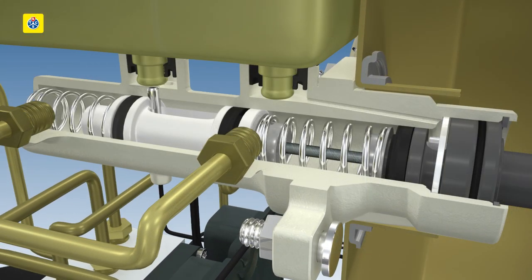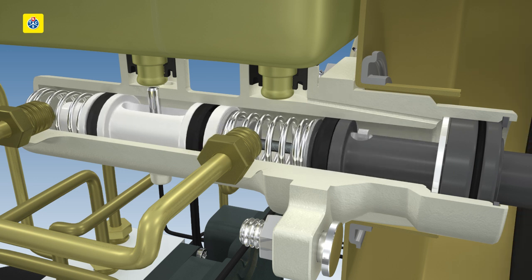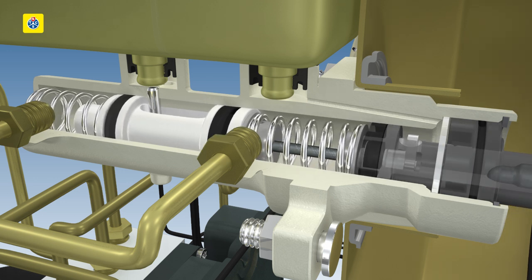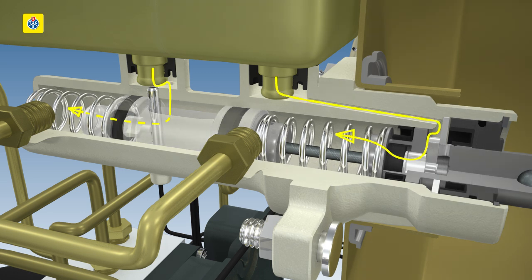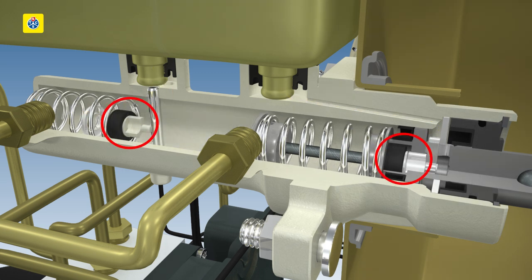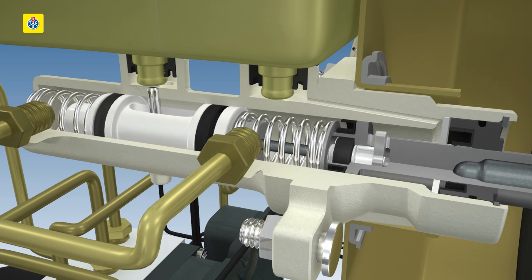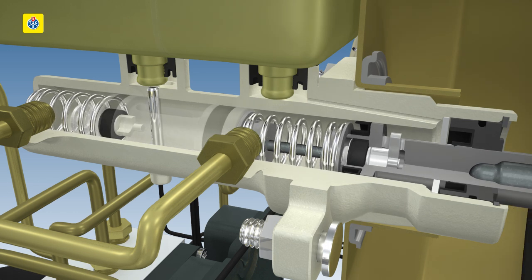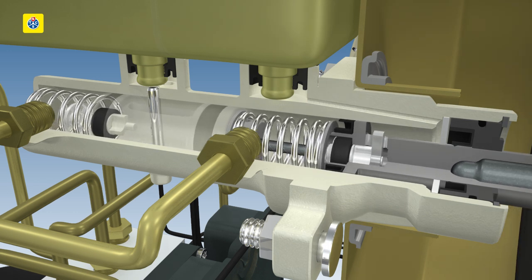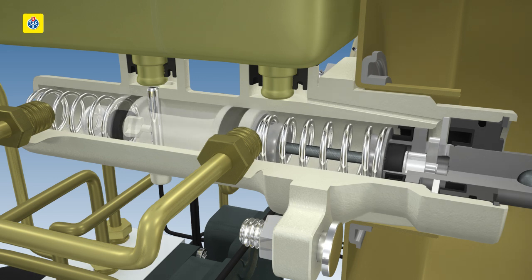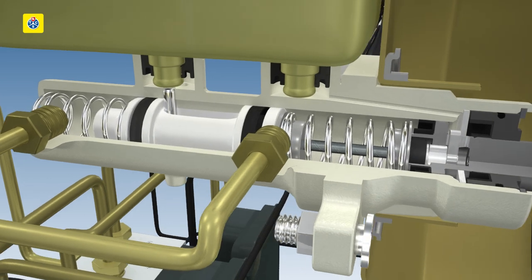The master brake cylinder pressurizes both hydraulic brake circuits through the movement of two independent pistons. The brake fluid flows internally to each piston through an after flow valve. These valves are closed during the braking phase and open when not in use. The opening allows the volume of brake fluid to be equalized due to temperature changes or lining wear.